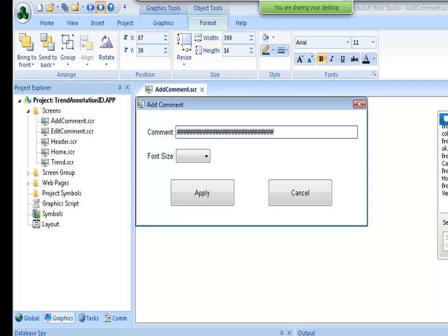How much data can be saved into the proprietary HST file? Very good question. The answer is we do not define a limit. The real limit will be the hard disk space in your computer. However, depending on the computer power from your hardware and the number of tags that you are saving into the HST file, this file can get really big really fast.